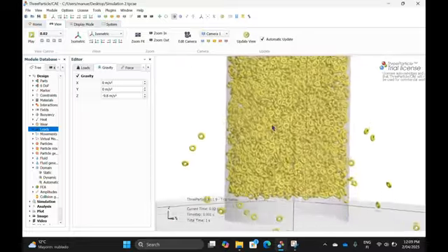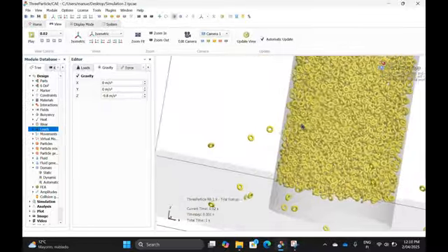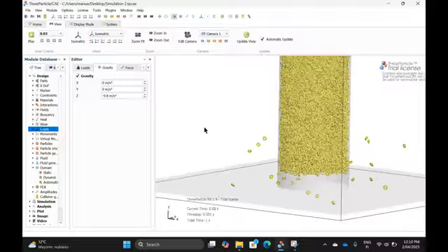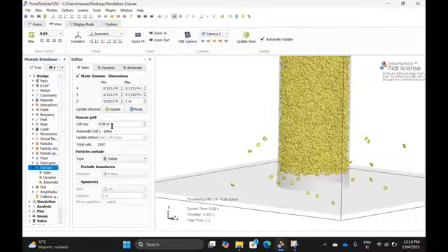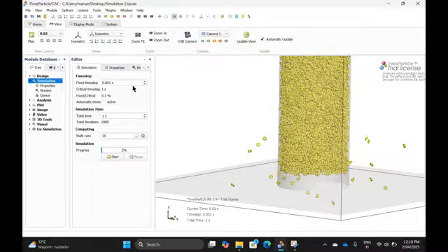I just put some values here so that I can proceed. And flexi is a little bit, I would say, here again with steel. Okay, I put some values here so that I can proceed. Okay, I have 40% of my critical time step here now. I can increase that a little. Okay, not so bad, about 30%. It's quite high, but hopefully it will be stable.